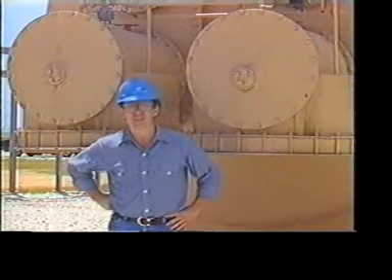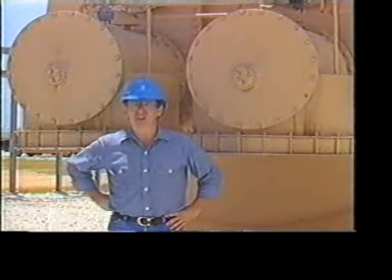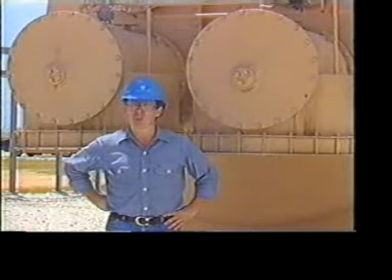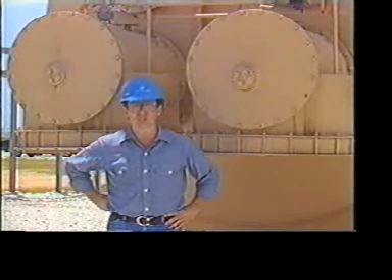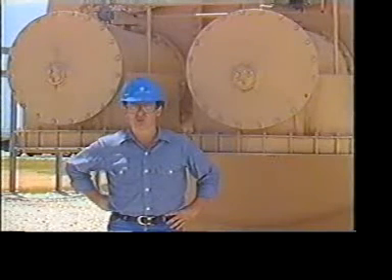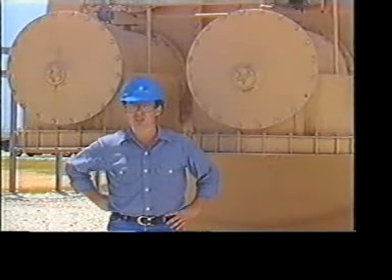resulting in lost revenue. Likewise, fire tubes should be inspected at periodic intervals. Since most emulsions being treated contain a certain amount of sludge and solids, the fire tubes should be checked for corrosion, rust, and any accumulation of scale.